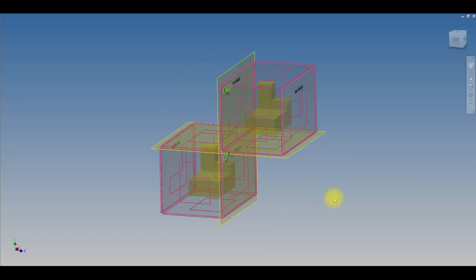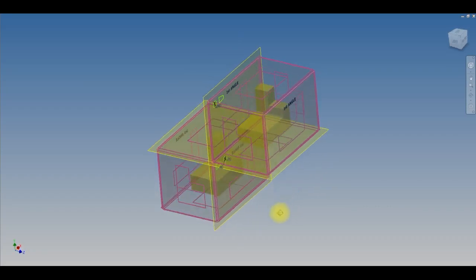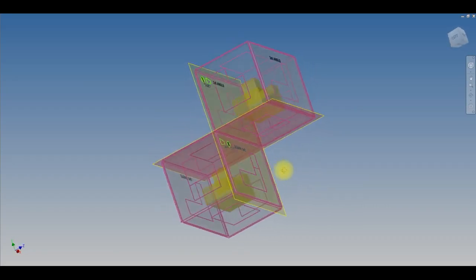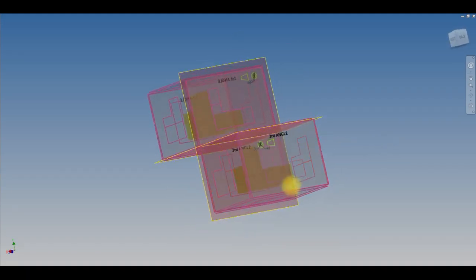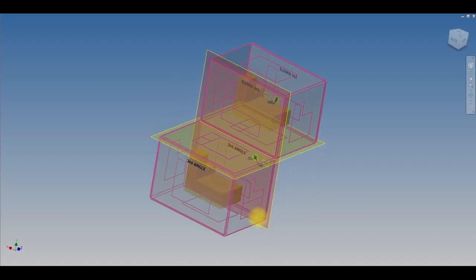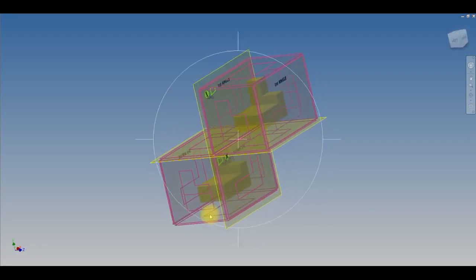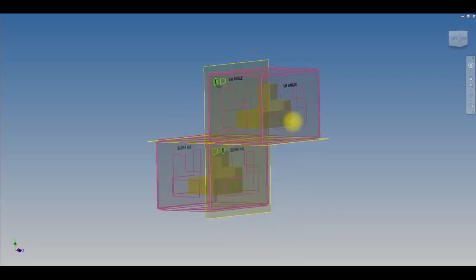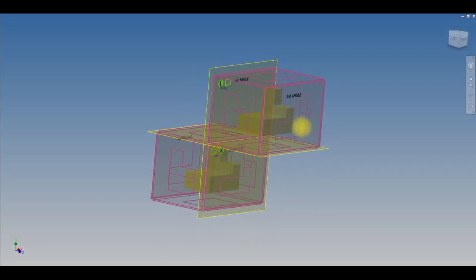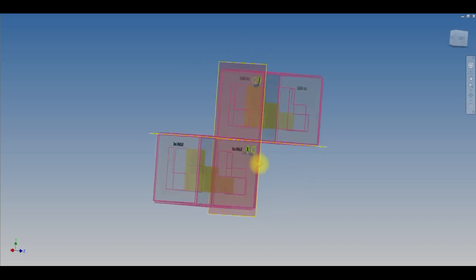We've got a first angle and a third angle. They're the 2 types of views that are used in drafting around the world. In Australia, we work in 3rd angle projection. So that's the one that we will focus on now. I'll explain a little bit about first angle projection, because it's basically the same, but you'll get a different type of view.